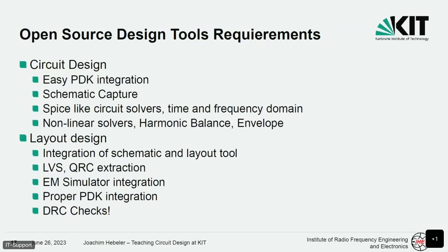And DRC checks. It's not just a checkbox, but we want to have the DRC checks that the fab will also do. We have seen in the past that there were issues with communication and documentation, where we used one tool for DRC and another tool was used by the fab. You send your layout out, you get a list of errors back, and you're wondering where do they come from? Because you're not just fixing some small bugs, you have to change your layout and you have to do all these reference checks again. Does everything work? Does this additional metal you introduce somewhere influence something? It's a whole lot of work we have to do, so we want to have very trustworthy DRC checks for our layouts.